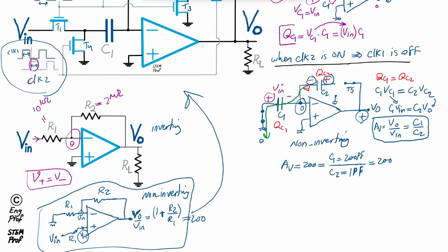So instead of, let's say, 20 to 40% variation for the absolute value of resistors with these kinds of sizes that are going to be humongous, for the ratio of C1 over C2, the variation over temperature or other parasitic effects can be controlled to less than or equal to 0.1%. So it's actually a very accurate amplifier in terms of the realized gain.